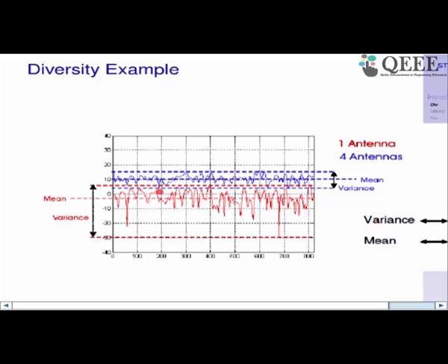Here, total variation is around 10 dB from 5 dB to 15 dB, but the signal is never less than 5 dB. You see, here it was 1000 times smaller, but here it is always greater than 1. 5 dB would correspond to roughly, I would say, 3 to 4 times what you had got at a single antenna. So you see there is a significant improvement in the received power, and that is the concept of diversity.